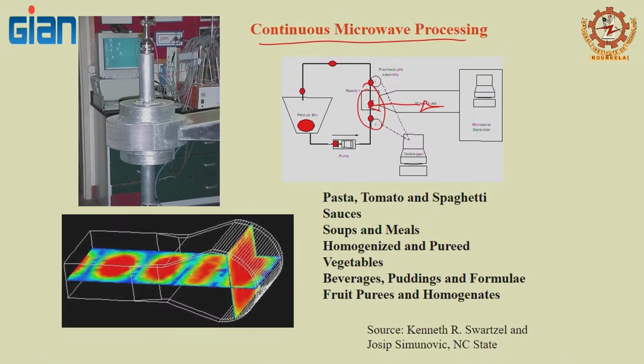In this example, your soup may be flowing here, and the microwave is applied here. Then you have a holding tube, a cooling section, and aseptic packaging, and so on. So it is a continuous method of processing.